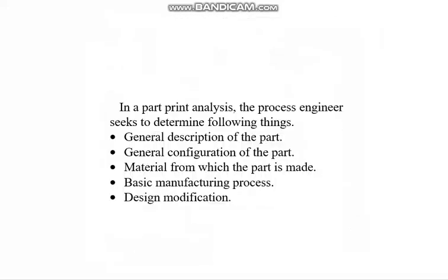Now in the part print analysis, the process engineer seeks to determine the following things. What is the general description of the part? What is the general configuration of the part? What is the material from which the part is made? What is the basic manufacturing process? Then what are the design modifications which they should request?